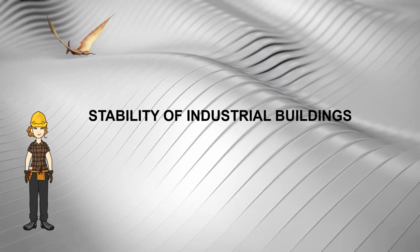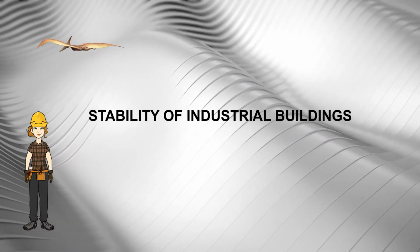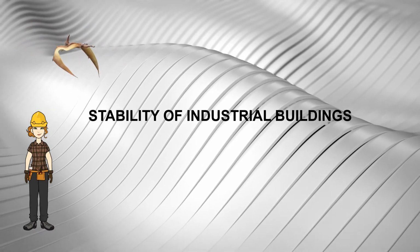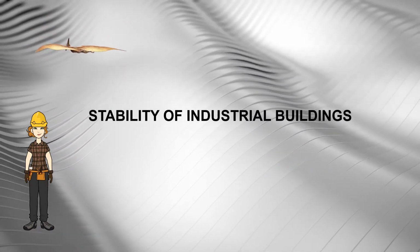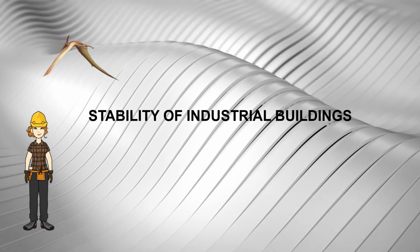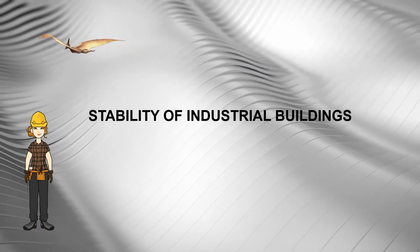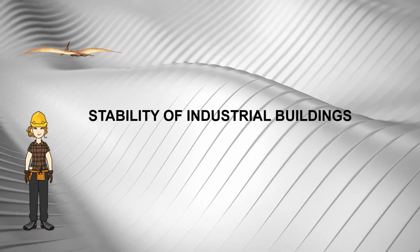The rafter bracing itself provides restraint to the heads of the gable stanchions. The brace and base provide anchor points to which the longitudinal rafter stabilizing ties, which are usually the purlins, are attached. During erection, bracing facilitates plumbing and squaring of the building as well as providing essential stability.